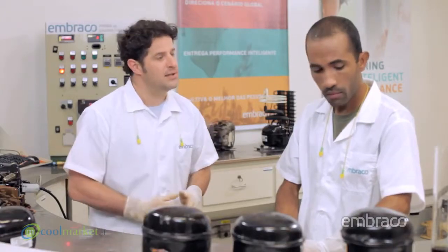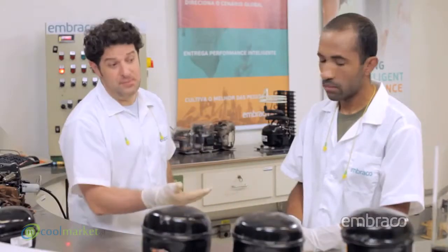Yes, Mark, the problem is that the antifreeze, being an alcoholic solution, as it's added to the cooling system, chemically reacts with plastic components inside the compressor, making them fragile and brittle, compromising their quality and durability. Furthermore, it may generate changes in the chemical composition of the oil, causing it to lose its lubricating capacity.